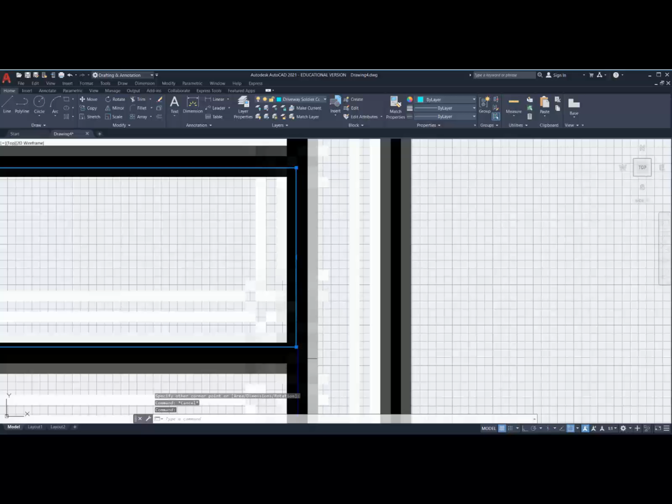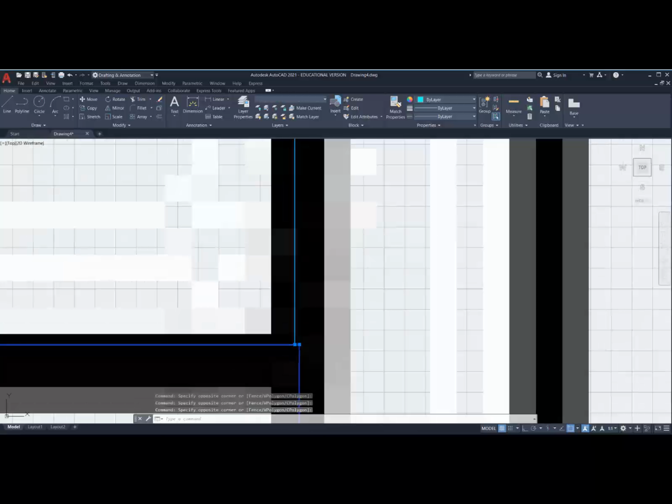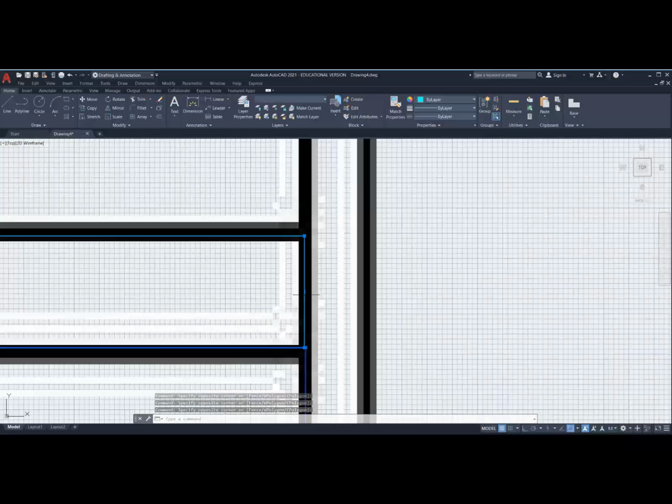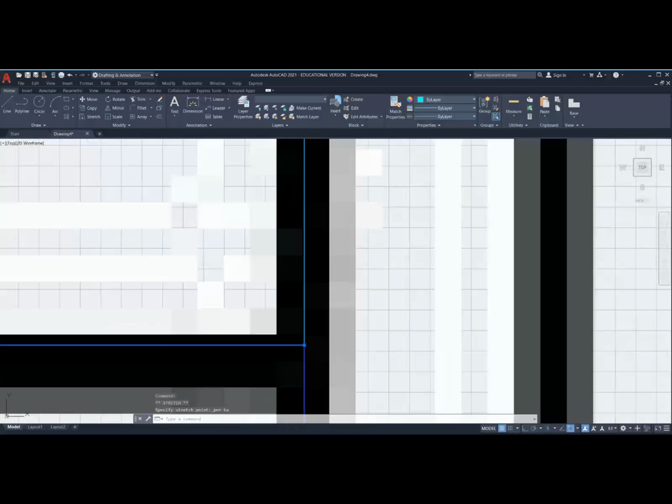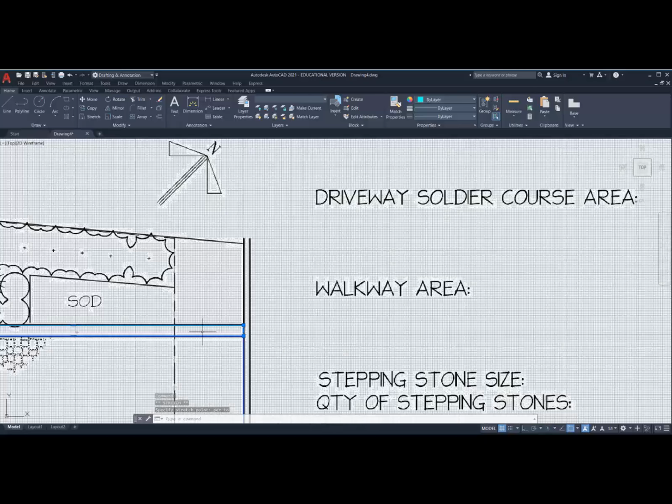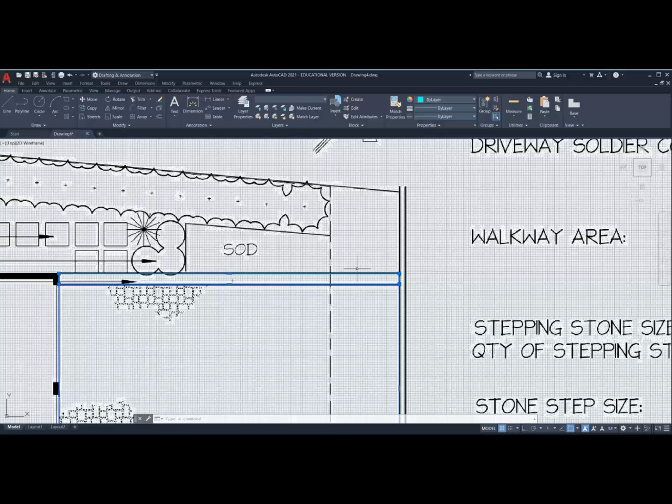Now, I'm going beyond what's really required in terms of the accuracy level, but it gives me a nice, accurate dimension. You'll notice that these two lines may not accurately overlap. Let me just pick both of them. See, the dots are slightly different, but I could, if I wanted to, click on the midpoint here and stretch it to be perpendicular to that line. And now it's right down to the point. And this is something that if I use this technique, I'm guaranteeing as accurate as possible a drawing in estimating.